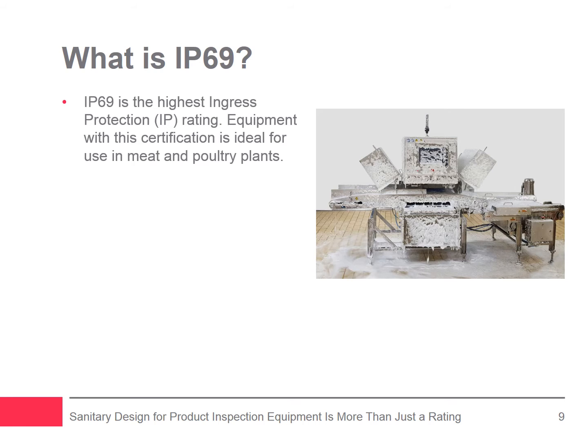The Ingress Protection (IP) rating system is an internationally recognized scale that relates to proven protection against environmental factors such as liquids and solids. Ingress protection ratings can be identified by the letters IP followed by 2 numbers. These numbers define the amount of protection a piece of equipment has against specified elements and its ability to resist foreign matter that could otherwise get inside the equipment and cause it to fail. The first number refers to the amount of protection an enclosure has against solid matter such as dust particles, while the second number defines the level of protection against liquids. The higher the number, the greater the protection.